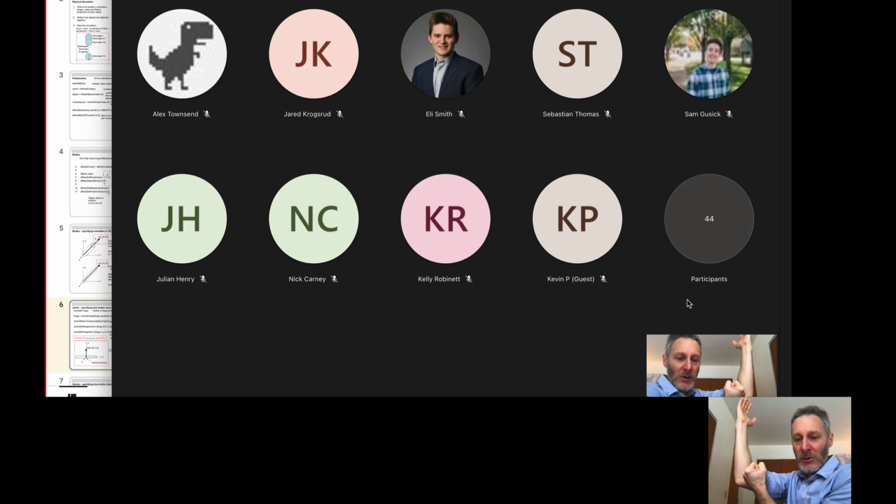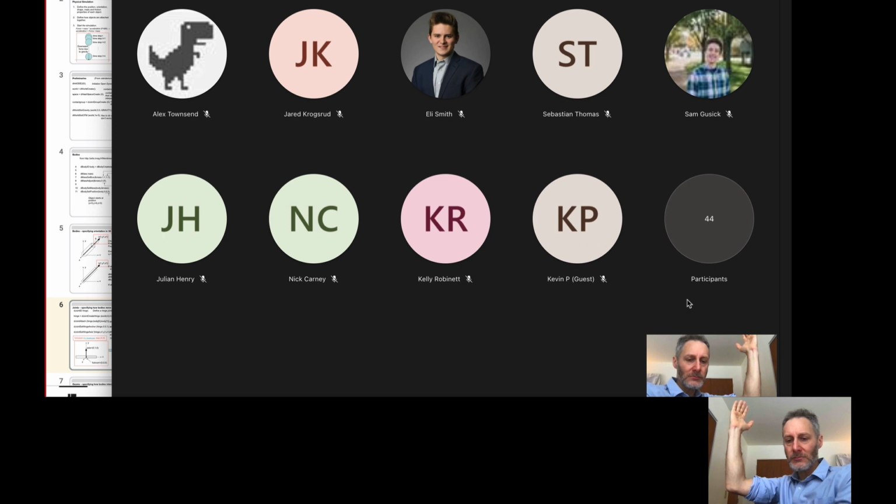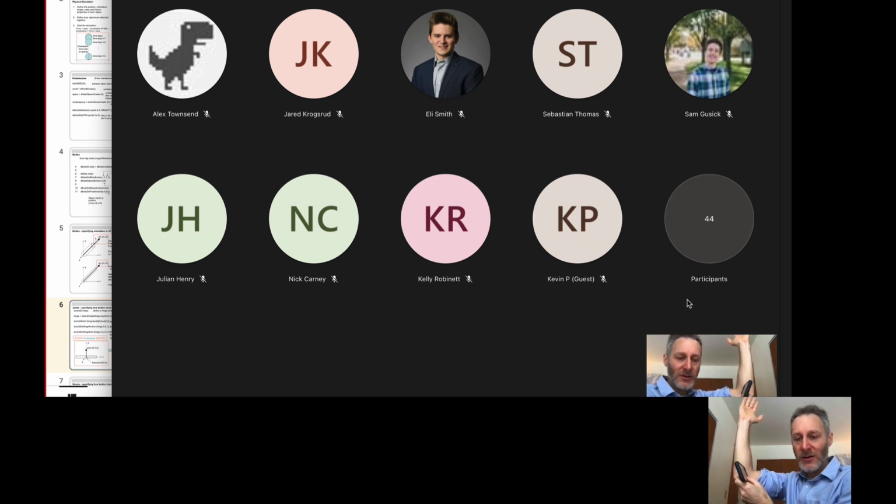So when we're defining a joint, you can define a new data structure called the joint normal, which is a 3D vector. And the direction of that vector defines the 2D plane that the two objects are going to rotate through. So if I want these two objects to rotate through the plane that's parallel to the screen, I can define a joint normal that is pointing into the screen. This vector is normal to this plane here.